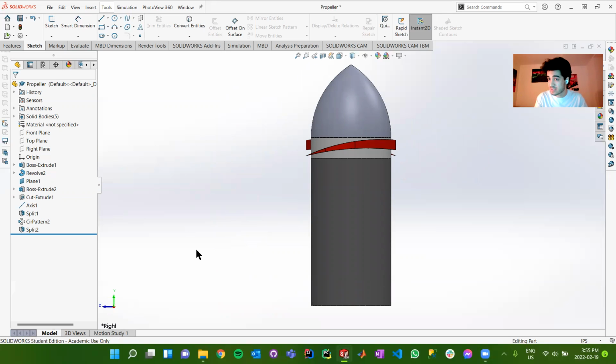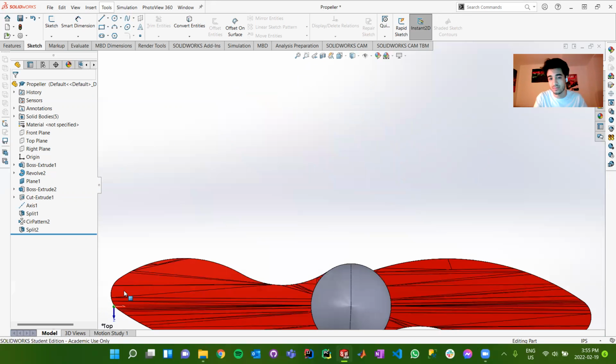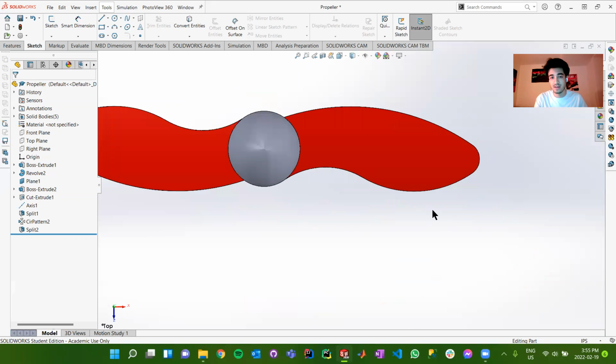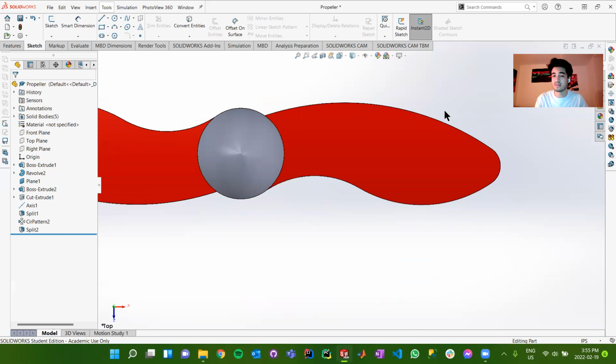Now, the next step is seeing, okay, where could we cut this from next? Well, if we do a Y projection, or if we look along the Y axis, you'll notice this shape isn't terribly difficult to create, a sort of free flowing shape, right? It's just one big arc, and you can essentially implement a couple of tangency constraints to create this nice free flowing body.